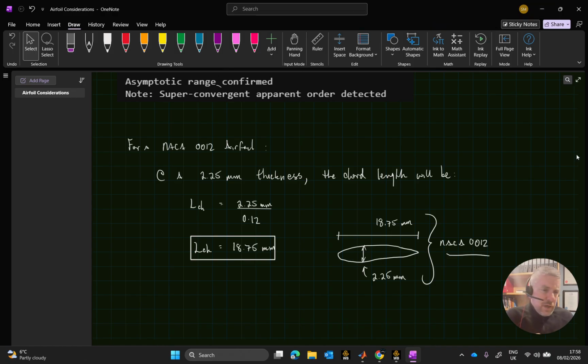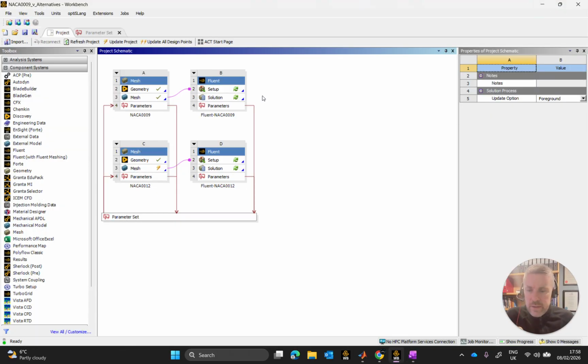Okay, so what I'm going to do there, we're just coming up onto half an hour now. I'm going to cut this video here, having set this up and determined what our NACA 0012 dimensions are going to be. In the next video, we'll go into Airfoil Tools, put that into the 4-digit generator, get the points, and repeat what we were doing in a much earlier video and bring the new geometry in. Then we'll match the mesh of the new geometry in system C to what we had in system A, and let's see how the two compare.